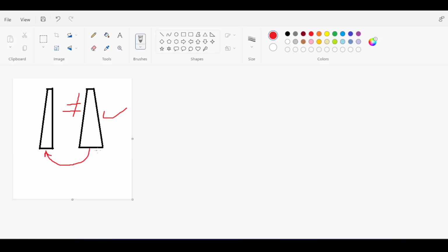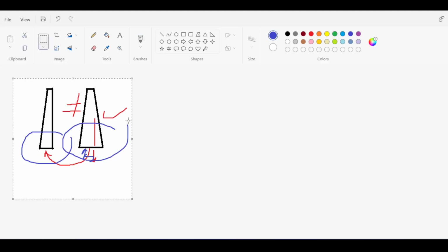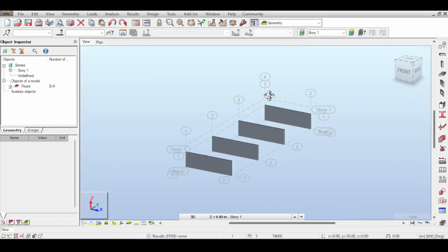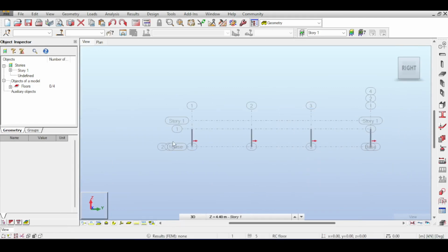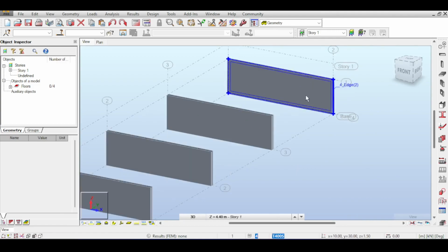Reason behind that is because when you design, for example, you want to calculate the vertical steel in the wall, then of course one of the factors that are included in calculating this steel is the moment arm, which is the distance between the concrete compression block and the tensile forces. So basically this. And this distance is all what matters in designing concrete. So I think that those two are going to approximate each other. So I hope that this little theoretical background could help you understand why I'm going to basically let this one slide. All right, now to continue, now I'm going to fix all of them and I will revisit this later because there is a lot of nice things I have planned for this wall.